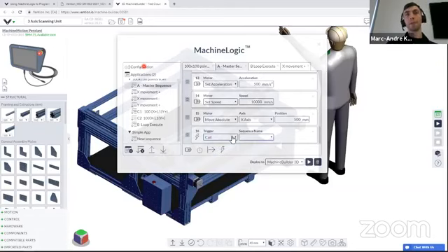And also, after this movement, if you want to call or execute another sequence, the difference between the two is that call will make the other sequence be activated in parallel, as execute will put it one after the other. So if you execute the next sequence here, as soon as we get to this step, it's going to fully execute this one before you do something else.